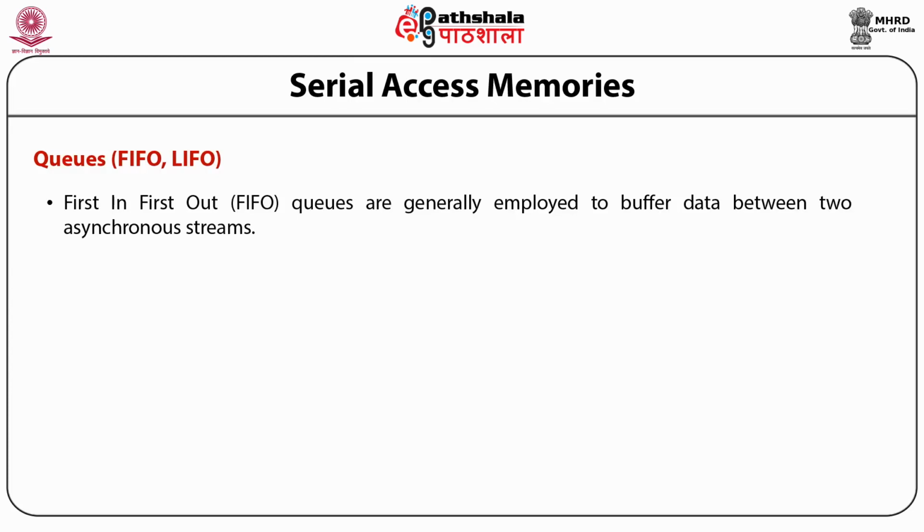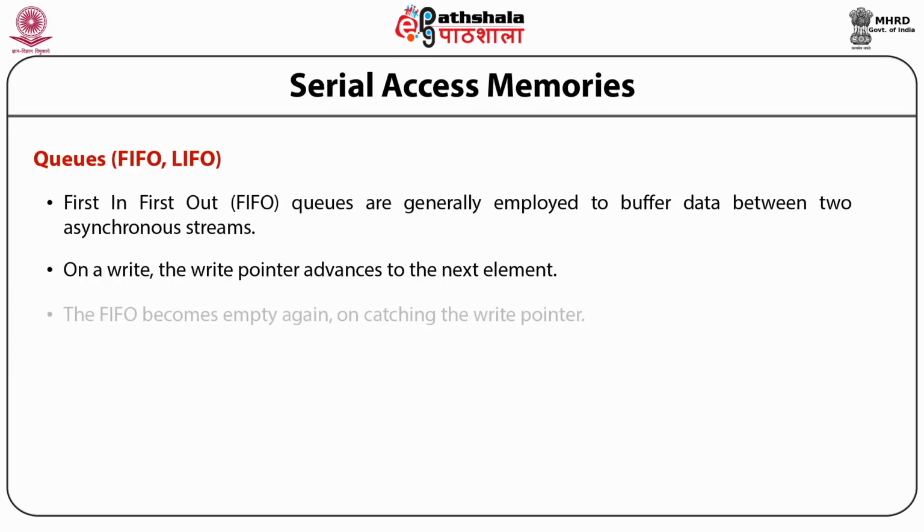FIFO becomes empty on reset and both the pointers, that is read and write, are set to the first element. On a write, the write pointer advances to the next element. If it catches the read pointer, FIFO is full. Now on a read operation, the read pointer advances to the next element. FIFO becomes empty again on catching the write pointer.